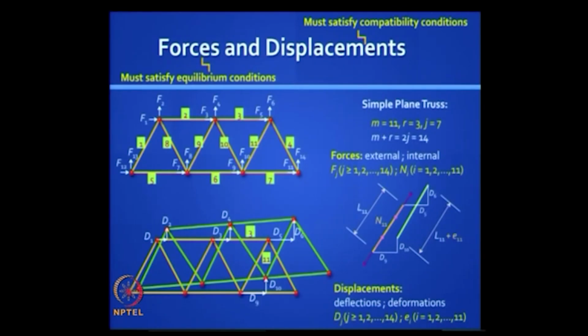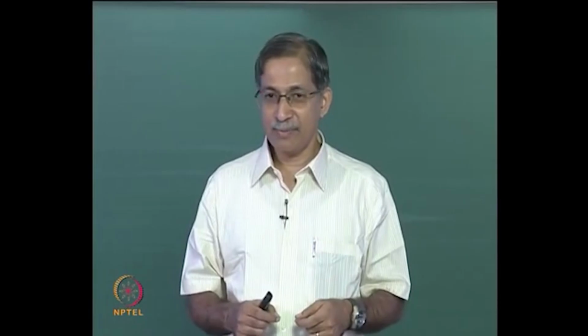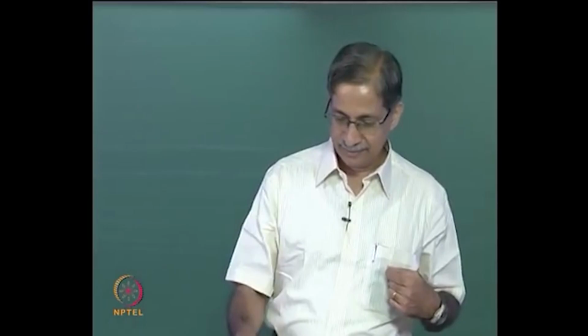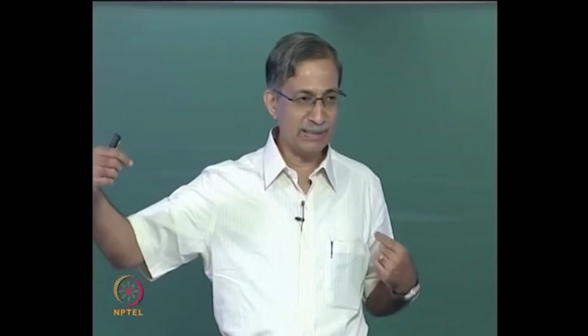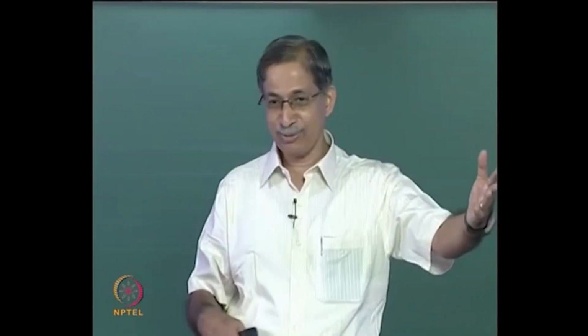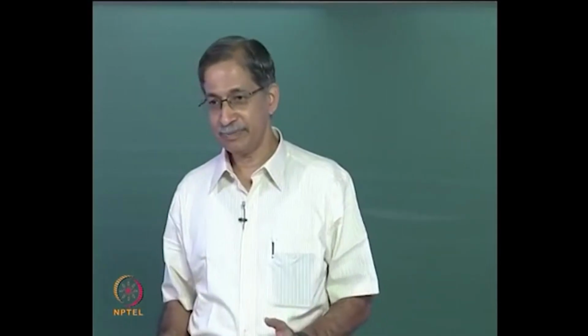But at the element level, you pull out one of those truss members, that element has its own internal force, okay, which we will locate at the ends of the element. You have 2 forces at the 2 ends, and somehow these forces are linked to F1, F2. So actually you have a transformation there itself. How do you convert joint forces on the structure to element level forces in different elements? You can see the potential, and the basis for that must be equilibrium.